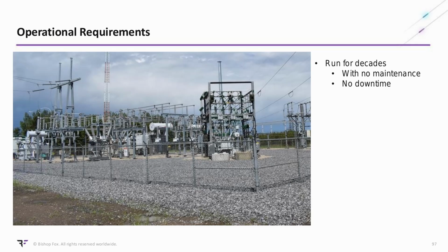You can't just go to a Best Buy and buy a computer and put it in one of these things. They have to operate in hot and cold. There's no air-conditioned server room inside of these things. You can't have fans to cool down the computer. They have to be completely passively cooled. So these RTUs are really expensive because they're rated for exactly this, right? They have to run for a really, really long time.